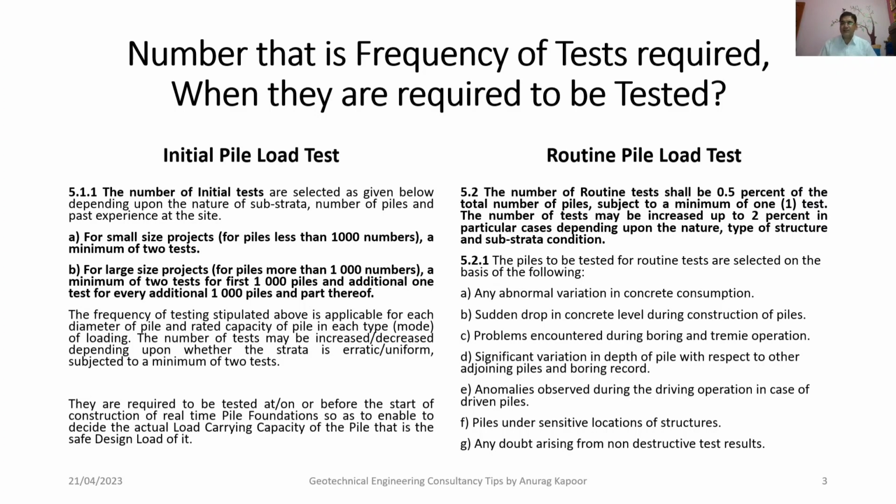So in those very sensitive locations, piles are required to be tested so as to observe the worst case scenario at that particular site. G, the seventh one, any doubt arising from non-destructive test results. That is, whenever pile integrity tests are done and we find some abnormalities, then we need to decide that this pile should be tested.